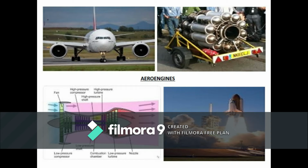Due to the introduction of one more turbine, which is absolutely free, there is no coupling with the main turbine. This free turbine is driven by the hot exhaust gases passing through the turbine, and it is responsible for driving the main rotor blade and tail rotor blade. The main rotor blade is the main driving force, which also generates thrust force, and the engine thrust makes it move forward.